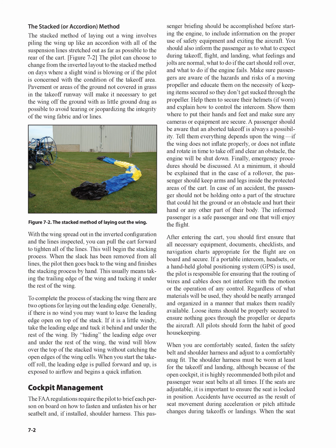what feelings and jolts are normal, what to do if the cart should roll over, and what to do if the engine fails. Make sure passengers are aware of the hazards and risks of a moving propeller and educate them on the necessity of keeping items secured so they don't get sucked through the propeller. Help them to secure their helmets, if worn, and explain how to control the intercom. Show them where to put their hands and feet and make sure any cameras or equipment are secure.